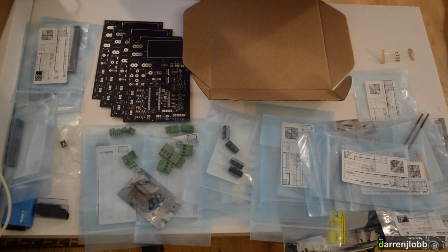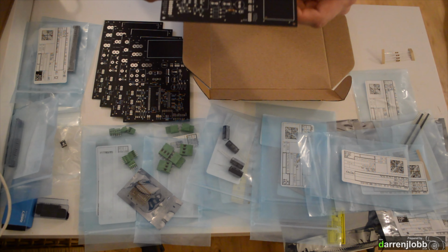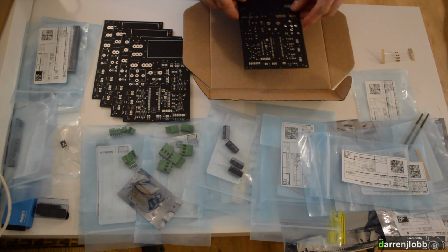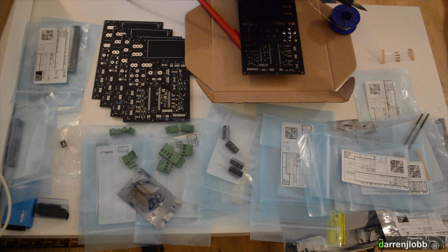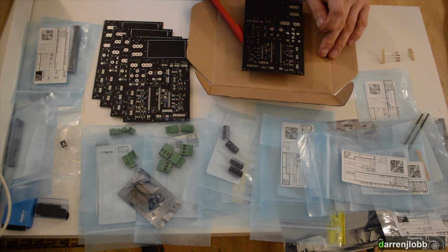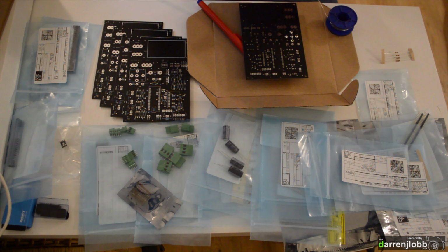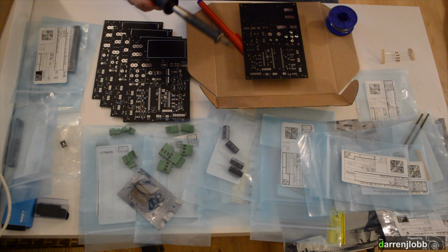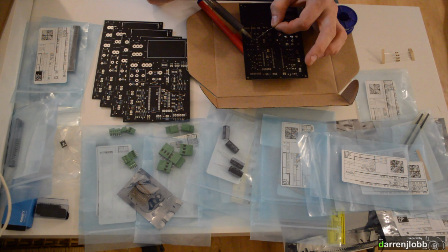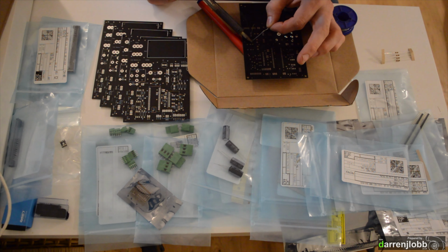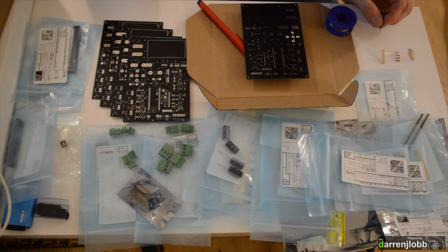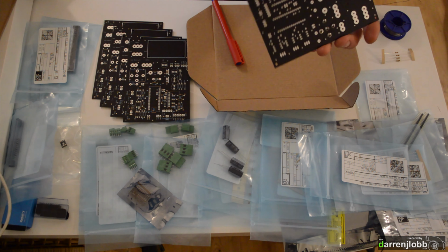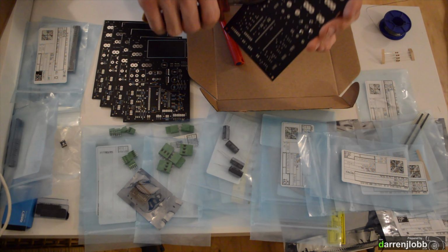Turn it upside down. If you put a little bit of bend on the legs, it won't fall out. Bend it over and put a blob of solder on each one. By the way, you will notice this soldering iron is absolute trash. I would recommend buying a decent fine tipped soldering iron for this type of job. Luckily this board doesn't have a lot of super small stuff, so you can get away with your agricultural spec soldering iron like this one, but it's not ideal by any means. But it gets the job done. And you can just use a pair of snips to cut the legs off again afterwards.